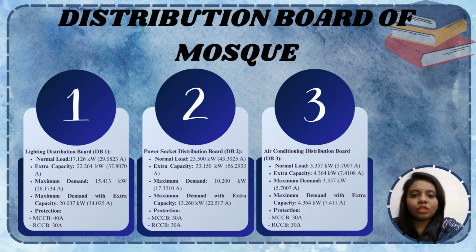Each DB is carefully planned to handle its respective load and peak demand, ensuring efficient power distribution while maintaining safety through appropriate protection devices like MCCB and RCCB. This ensures efficient and safe power distribution within the MOSC, with the sub-switch board SSB3 considering this load for easy management and protection.